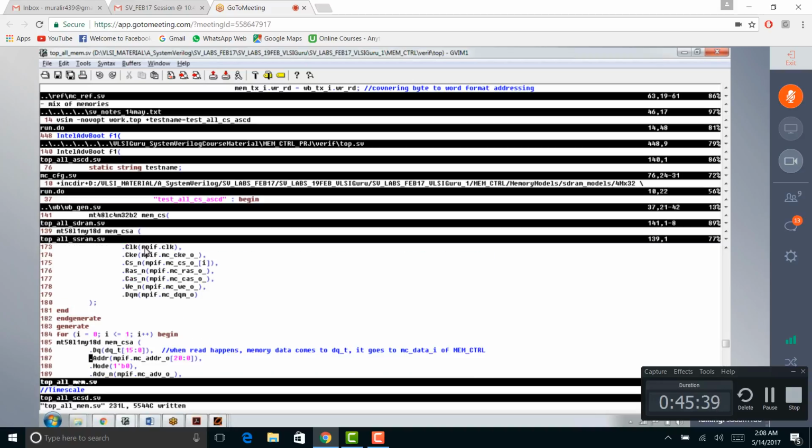So the only thing I have to change is, instead of 0, it will be 6 to 7. Is this clear to you? Now, is this the only thing I have to do? No. I have to go to the Wishbone generator. I have to, of course, create a new test case like I did here.